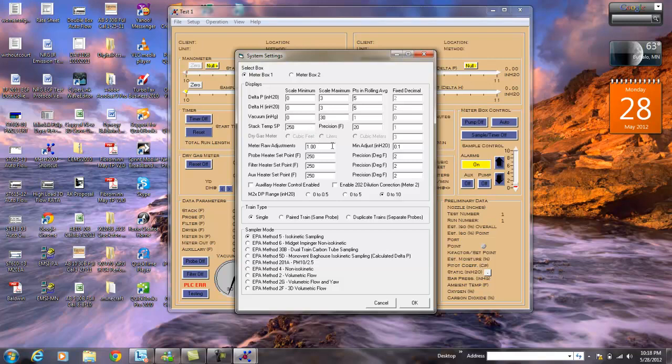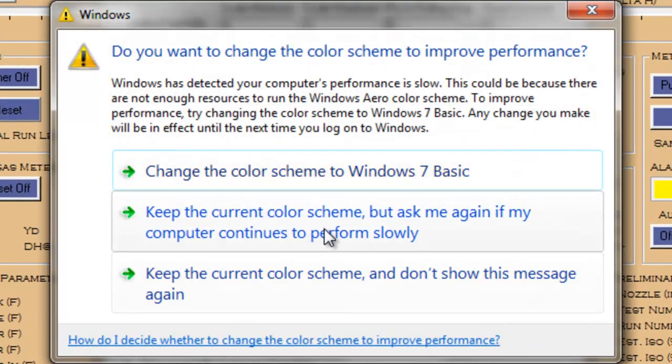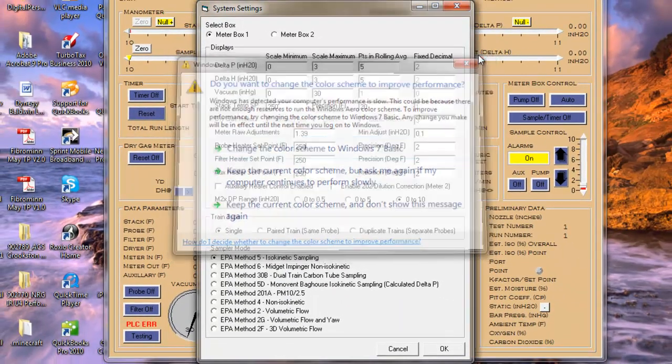And one would need to look at the raw master factor adjustment on the Autobox. Some of them are 1, some of them are 0.98, and a lot of them are 1.39. In this case, we'll put in 1.39 off of Autobox 4. That is right on the box. It's a constant number that's always used. It's basically, it has to do with the hardware, so that number remains constant for the box. I don't know why this is doing this, but we'll close that one more time.